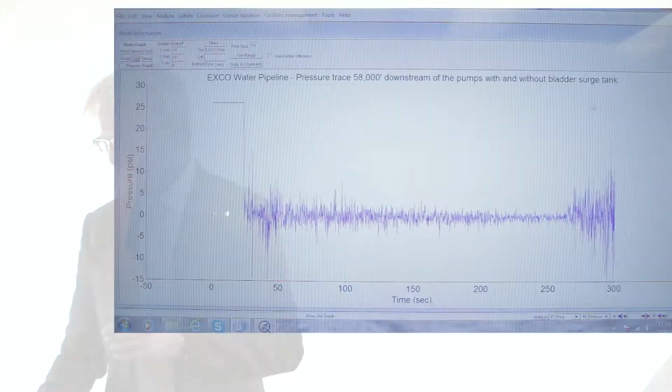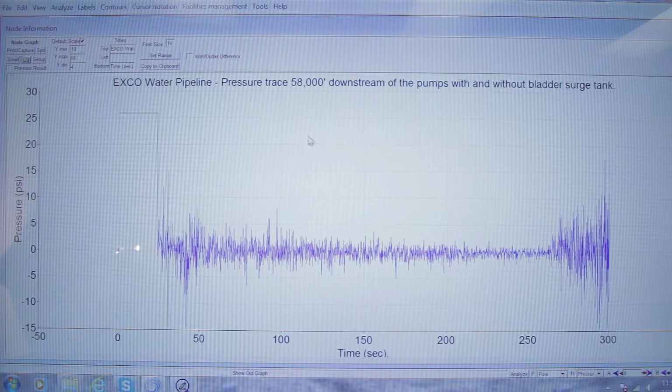And this again is ductile iron pipe in this 24-inch line. The pipe itself might be able to handle a full vacuum, but the fittings and seals for ductile iron pipe can only handle, say, a -6 vacuum condition. So we're going to go in and solve that particular problem in the field.